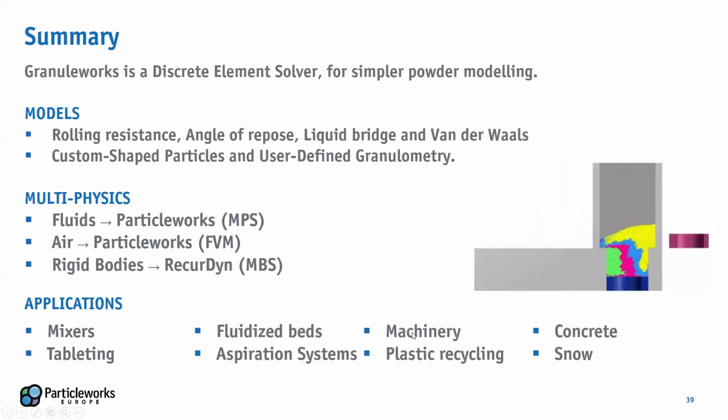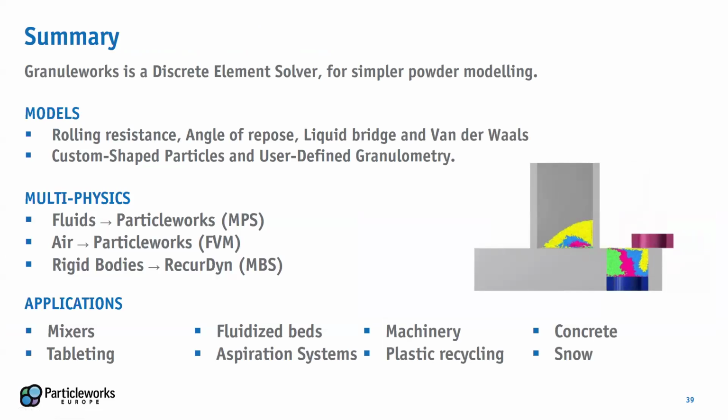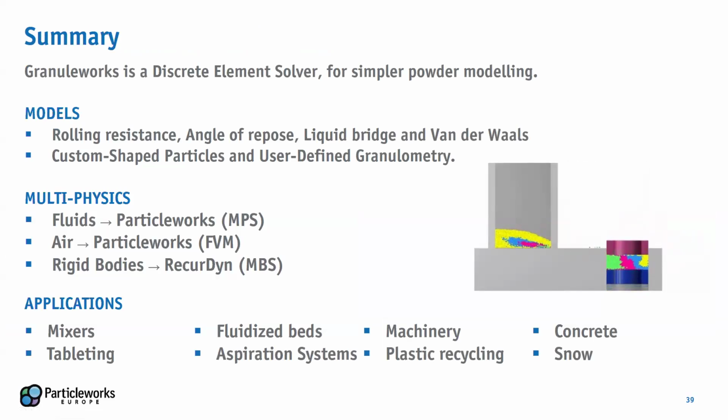So just to summarize a bit, and then I would like to open up a Q&A session so that I can better address your points. To summarize, Granuleworks is a discrete element solver. It solves Newton's laws of powder interaction. It integrates rolling resistance, angle of repose, liquid bridge, and van der Waals models, as well as custom shaped and user-defined granulometry.